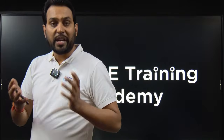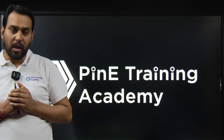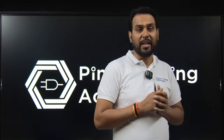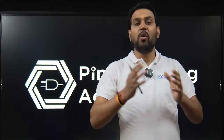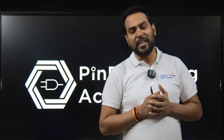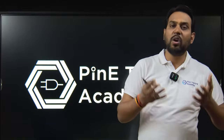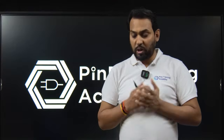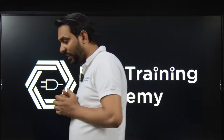After this, we discussed the resistor, capacitor, and inductor, and how they are introduced in a layout in VLSI. In a layout you have metal routing, connecting one point to another, so you require a conductor and you use a metal route. A metal route has sheet resistance, and on the basis of length and area you can describe the resistance. So of course you have an IR drop. What is the voltage? We discussed this by Ohm's law, what Ohm's law means and how we can use it.